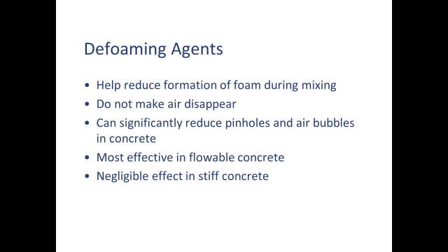But the defoamers do. They break the surface tension, so the bubbles basically burst, and the air that's trapped inside the bubble can coalesce into bigger bubbles and then move out of the concrete. So defoamers are most effective when you're trying to make very flowable, pourable concrete, when you're trying to vibrate the concrete or making SCC. They have almost no effect when your concrete is so stiff that air bubbles are stuck. Because, again, defoamers don't make the air disappear. They just make the foam unstable so that the air inside the bubble can rise out on its own.